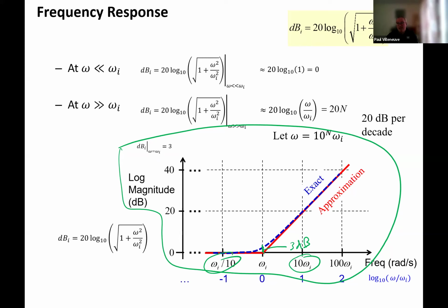That way I don't have any frequencies passing through that I don't want. So if it's a 500 kilohertz break frequency, you probably wouldn't operate it for systems that have more than 50 kilohertz or something like that, because you're going to have too much goofiness in your output to get real results.